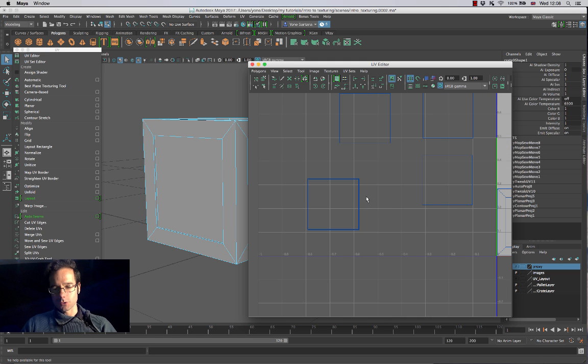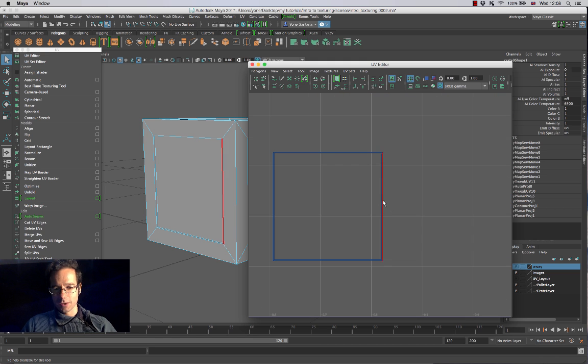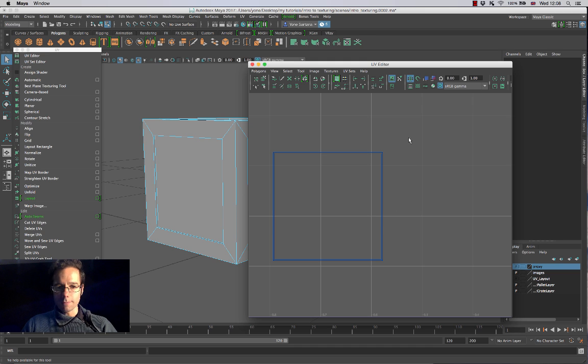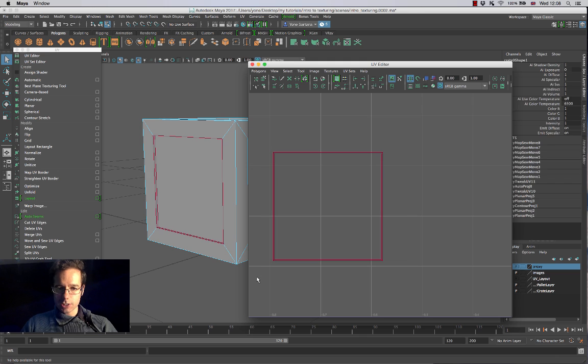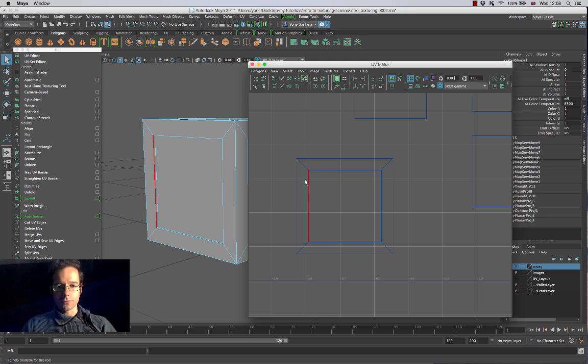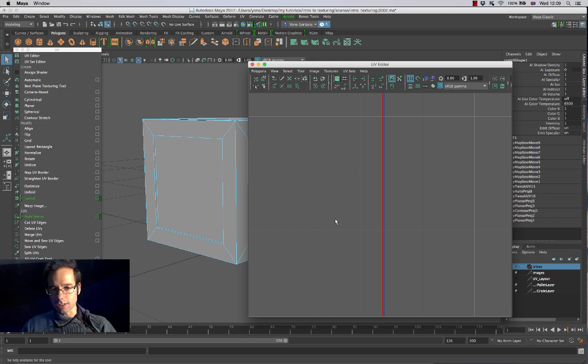Again, you have to start making those calls of seeing if that's the way that you should do it. Now, ring and loop are always going to be really useful as well, but you can also make selections like this. Like I can select all of this, the entire shape and edges, and if I do another Move and Sew, it's now going to move, and all of these interior faces, they've already been sewn together. And now I've just brought in this other UV tile over here. So very quickly I've made a little 2D version of this.